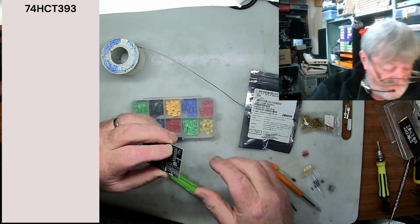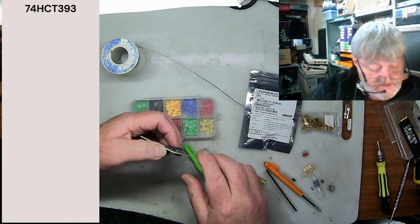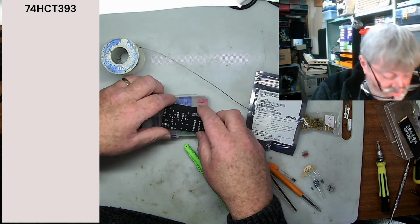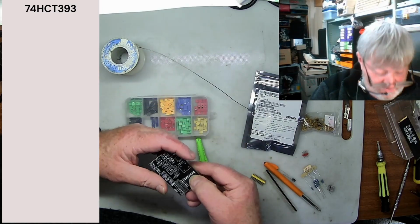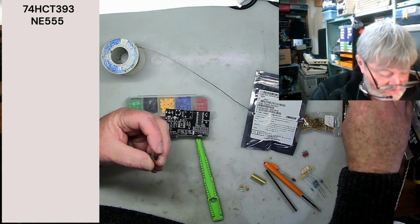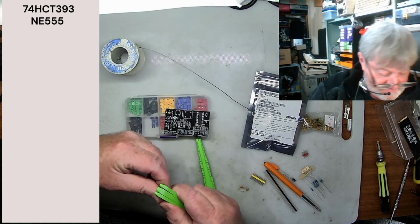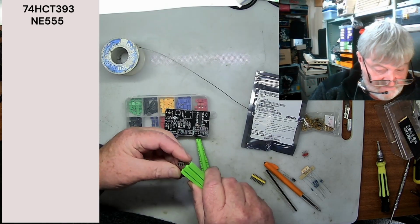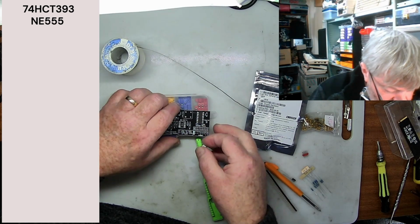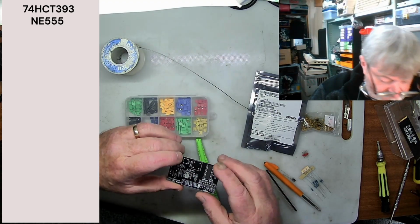So what I generally do is put something on the side, either a bit of blue tack or something like that, but generally if it's only one or two ICs, we could probably put the pair of them in there. That's the 555. The other thing you've got to realise is your ICs sitting in drawers, even if they're in static foam, you may find that the legs get a bit knocked around as well. That's a 555 and goes in there, pin 1, yep.